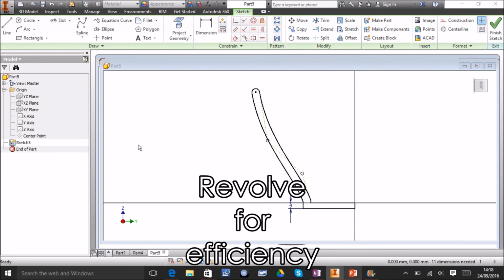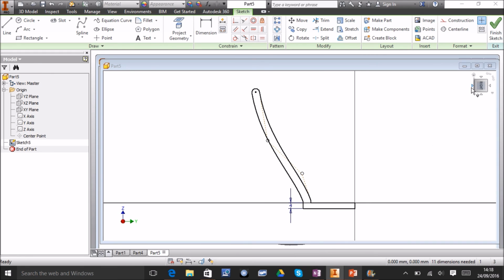So something else that we can do with the revolve tool is we can make sort of more complex shapes that are going to be hollow in one operation. So this is a sketch that I've got for a little teacup. Now I've made it up using the rectangle tool, and then I've used the spline tool to create this sort of more complex curve. I've offset it so that I've got a second curve that's copied, and then I've joined the two up with a little arc.